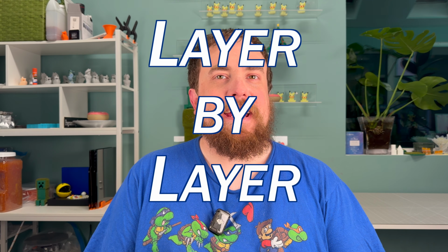Phil here in the layer by layer layer. For this video, I'm looking to make the fuzzy skin setting a little less fuzzy. This is a setting that I think gets ignored by many, but it's useful in both cosmetic and functional prints.